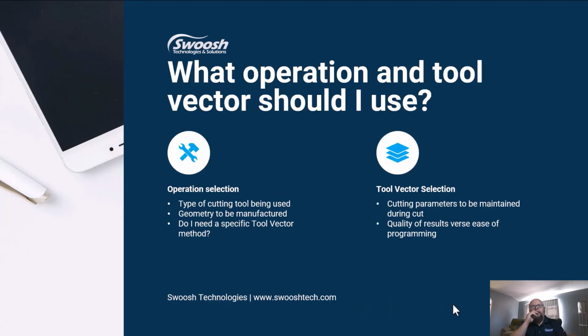So, again, talking about which operation and which tool vector control method should I use. Again, this goes back and forth. If I know that I need to use a bullnose tool, well, that rules out using a guiding curve operation. It's not supported. If I know I'm going to use a ball mill, then I know I can use surface area drive method, I could use streamline, I could use guiding curves.